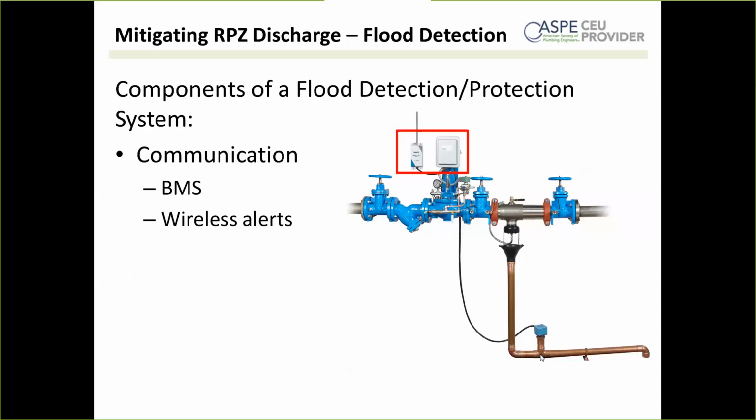The only caveat to that is if your problem is something like water hammer. Water hammer can cause spitting even if it's downstream of the check valve, because that pressure wave is going to hit the downstream side of that second check, and that pressure can actually migrate through that second check by pressing it further into the seat. So if you're having some trouble and you can't figure out what it is, and you think it might be something downstream like water hammer, a soft-seated check valve can take care of that, or you can do the thing that is built for it, put in a water hammer arrestor. It's not something I touched on, but it's certainly the appropriate solution to water hammer.